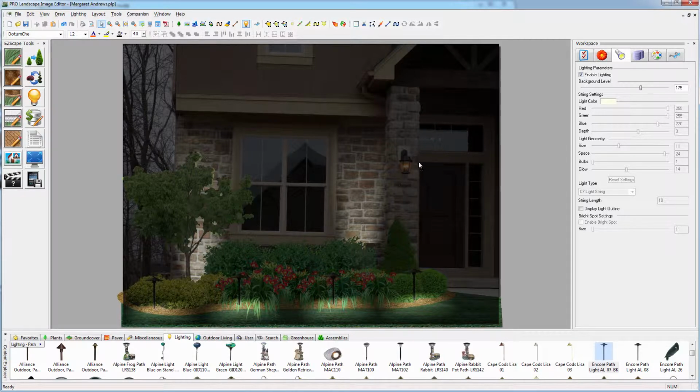Looks quite nice. Now we do have this porch light here that was built in, and so let's go ahead and light that up. We can click on the light polygon, and we'll just define an area for that light. We can see we're drawing as the light as we go, and we'll come up here and over here to the side of the fixture and right click to finish. Now the white dot again is our light source. Obviously in this case it's the bulb, so we just drag that up, and we can see it's going to be a little bit brighter here by the bulbs, and we have our finished lighting design. Quick and easy, fast and efficient, so we can add our lights that way.